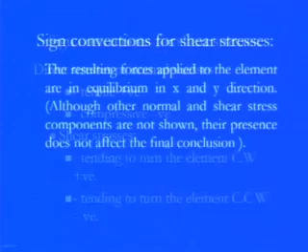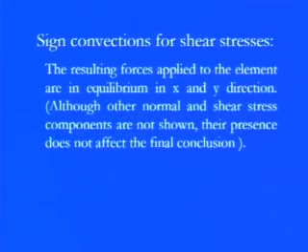whatever stress components are trying to force it towards the clockwise direction, consider them positive. And as we have seen in the previous case, the complementary shear stresses, which try to oppose that and rotate the object in the anti-clockwise direction, are considered counterclockwise, or we can say the negative direction. So the sign convention gives you the resulting force applied on any element which is in equilibrium, in the x or y direction, and tells you whether the shear stress or complementary shear stress is applying in the positive direction or not.